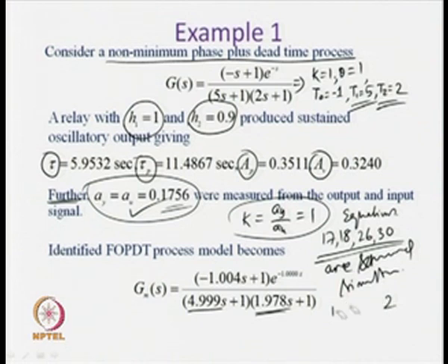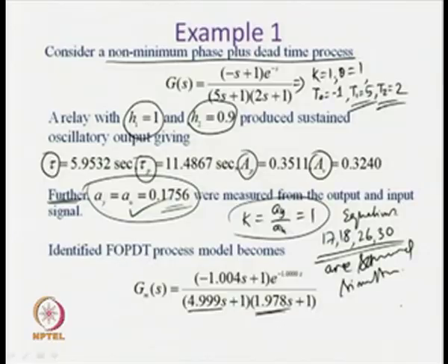So, using the identification technique, it is possible to estimate the parameters of a transfer function model accurately. This shows the efficacy of the powerful equations we derived earlier, based on the zero crossings and peak amplitudes of the output signal.